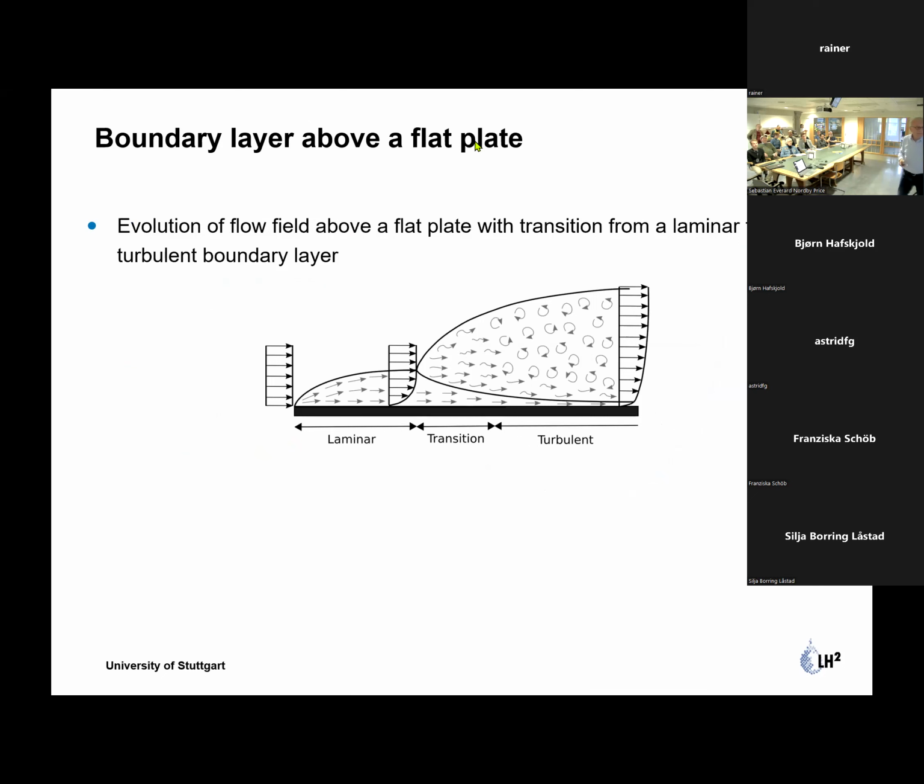You can be in the laminar regime and you can be in the turbulent regime, or you can be in between. And very important, I will come back to this later on. Normally we are in the turbulent regime, and then you have the viscous sublayer here and the turbulent layer. That means in the viscous sublayer, between the viscous sublayer and the solid, the porous media, you have laminar flow, relative structure, and above you have an optimal mixing related to the turbulent flow. That is the fully turbulent system.